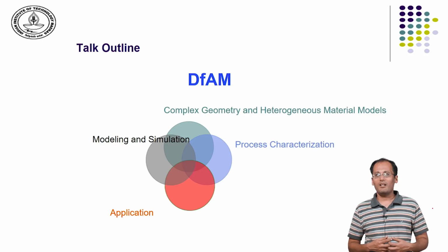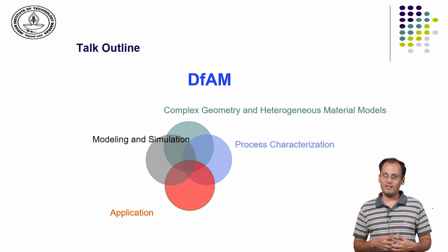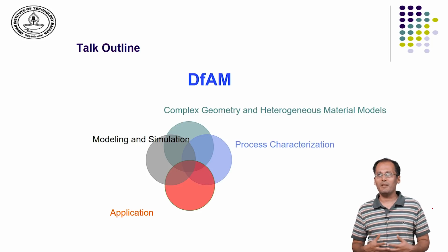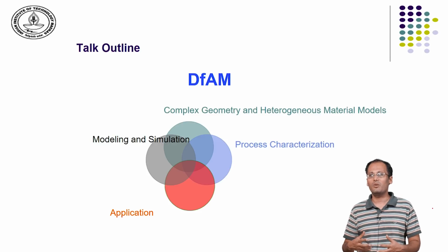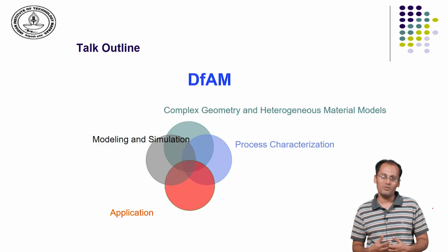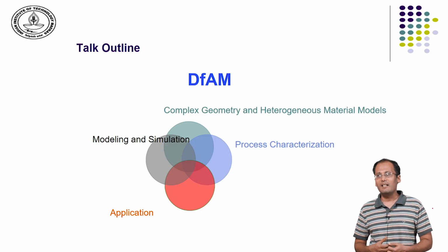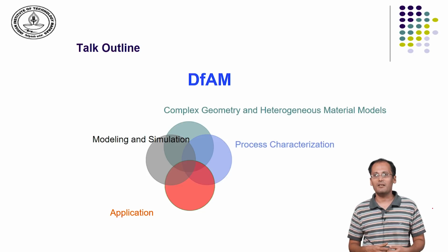So, we talk about topology optimization or shape optimization or generative design, where rather than presuming the shape, the shape of the object is generated based on the loading condition for which the part needs to serve. So, design processes like the generative design process need to be developed and integrated with the additive manufacturing process to enable very complex shapes.